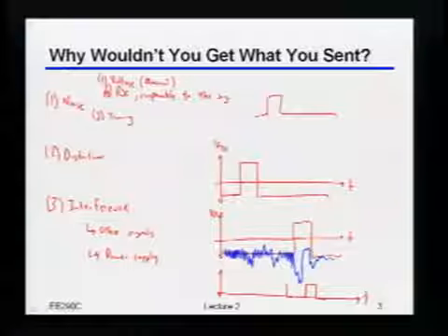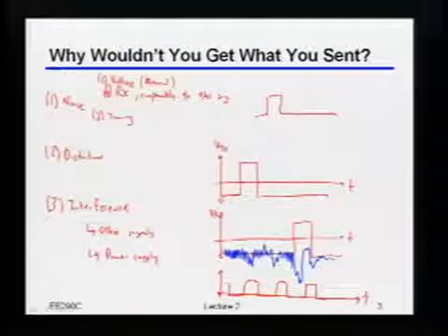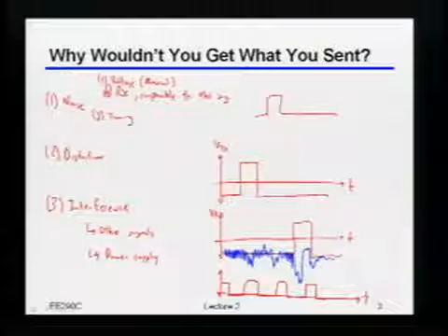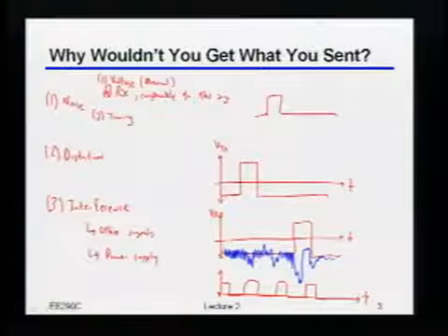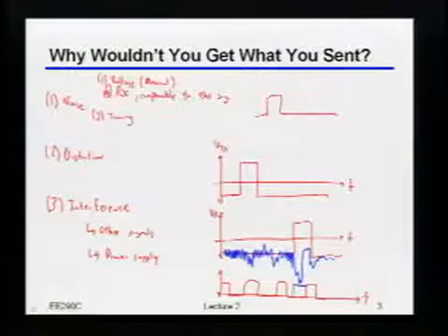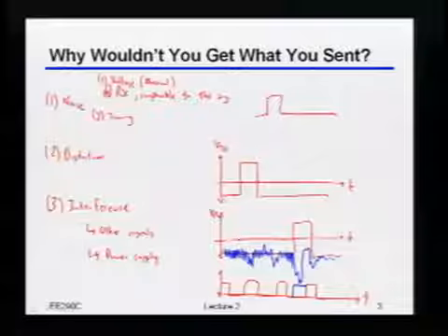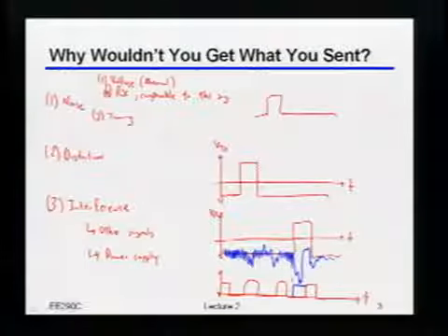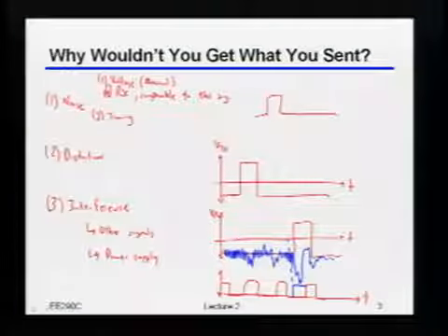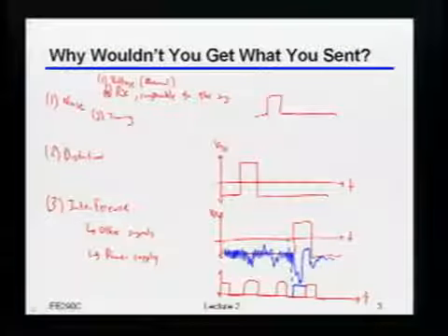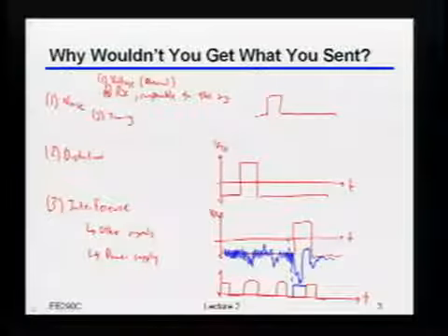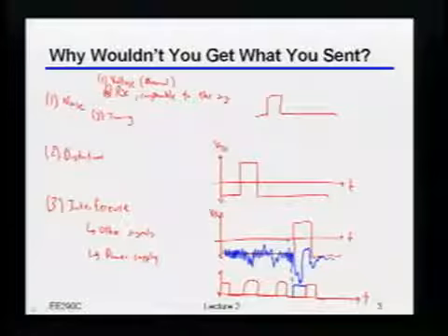So if I draw an ideal clock waveform like this, where this is good, well, just like I can get noise on my voltage, guess what? Due to some weird noise event somewhere, my clock could show up at the wrong time, right? And if my drawing was a little bit better, so that I didn't have to angle that thing, I would have made it really clear that that jittered clock, or that timing error, caused you to sample the wrong bit.